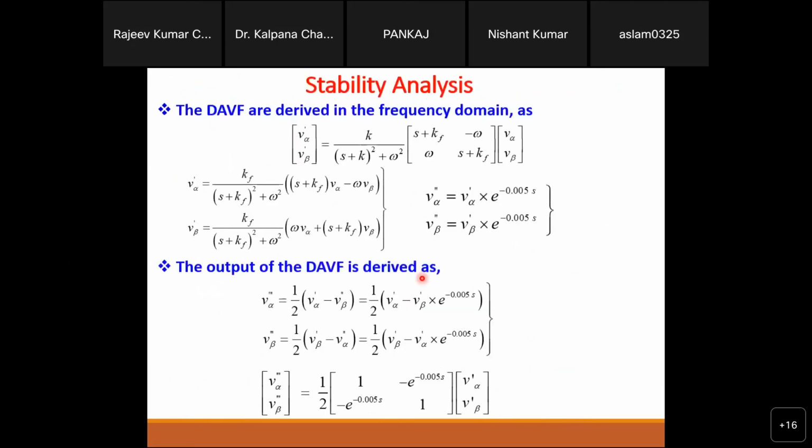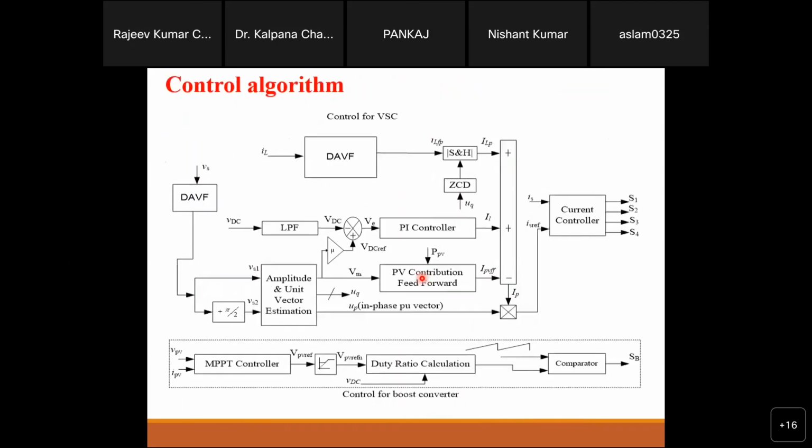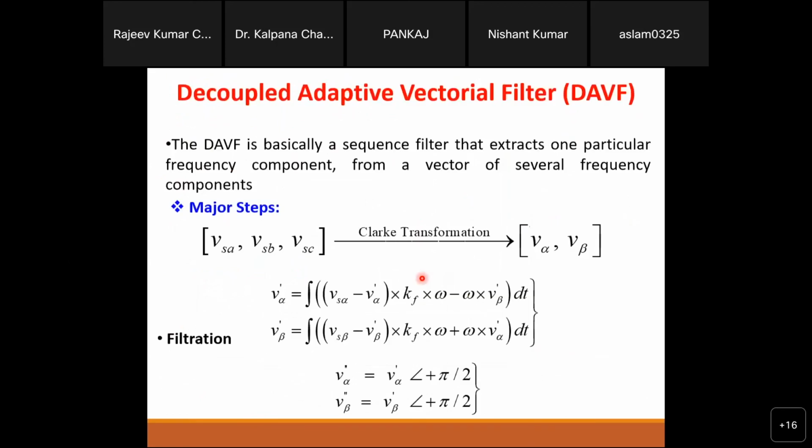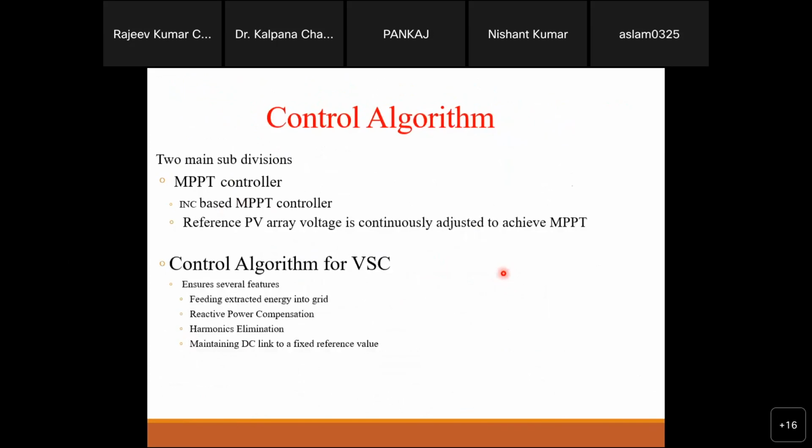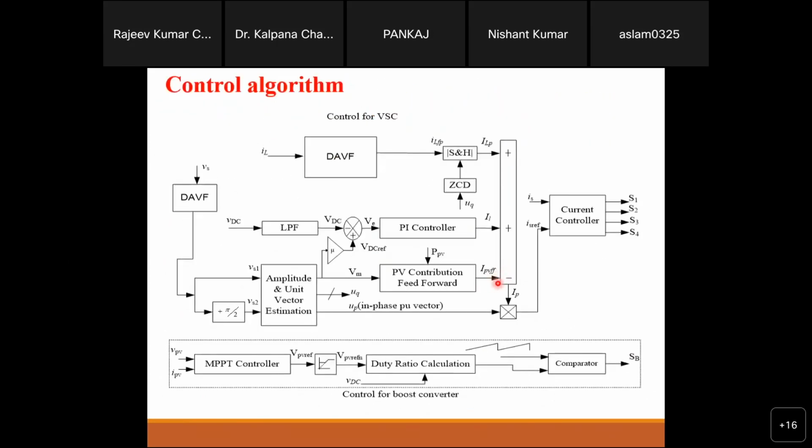If you have multiple sources also, for example a small hydro, right? That you will attach here. Small hydro will generate AC power directly, so you can attach it on the PCC directly. And then that will be considered in the grid as one component, the negative component. So that component will also be minus here. That's it, nothing else. Minus because this is the generated power.